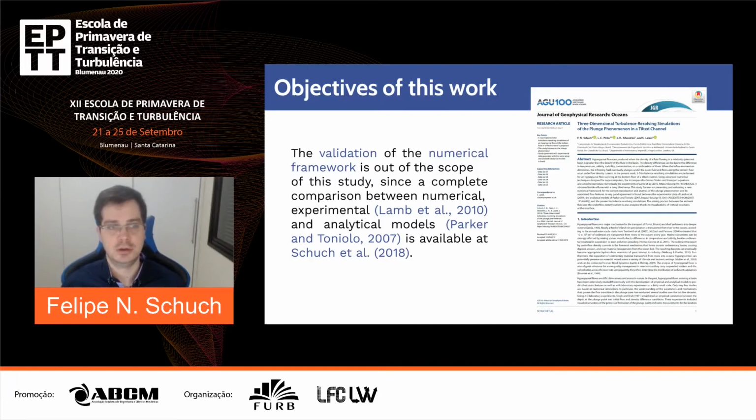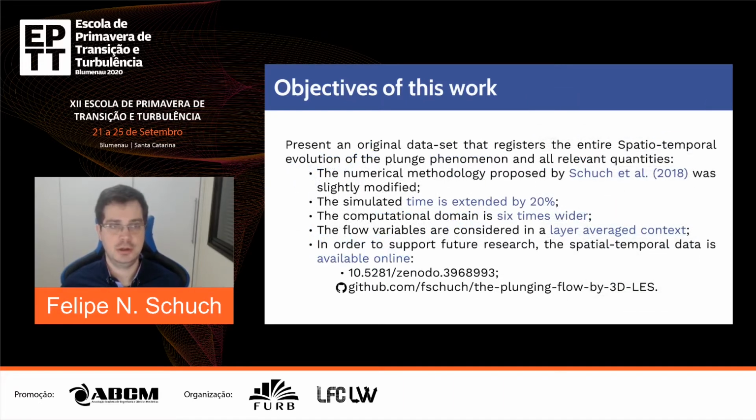A complete comparison between numerical, experimental, and analytical models is available in our study from 2018. However, we aim to present an original dataset that registers the entire spatio-temporal evolution of the plunging phenomena and all relevant quantities. So the numerical methodology proposed by our previous study was a bit modified. The simulation time was extended by 20%. The computational domain is 6 times wider, and the flow variables are considered in a layer-average context. And in order to support future research, all our data is available online.